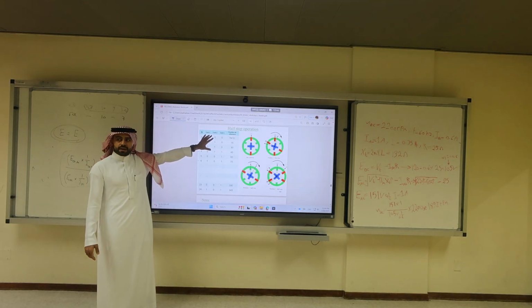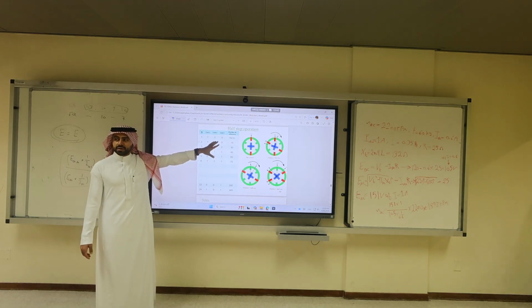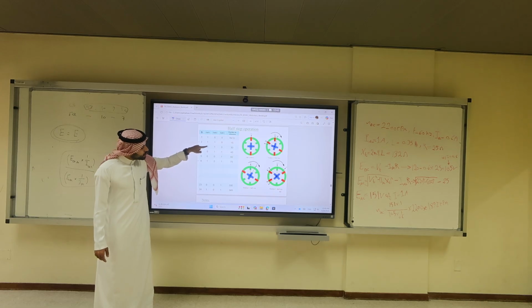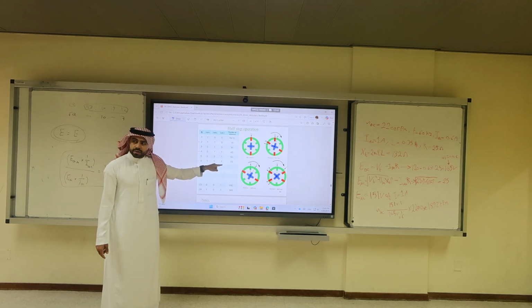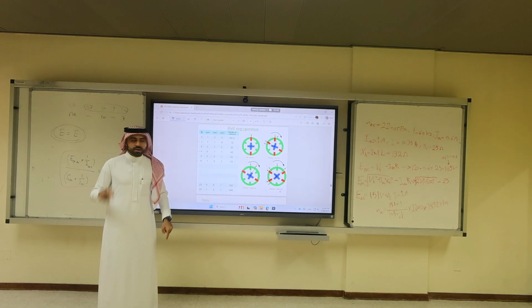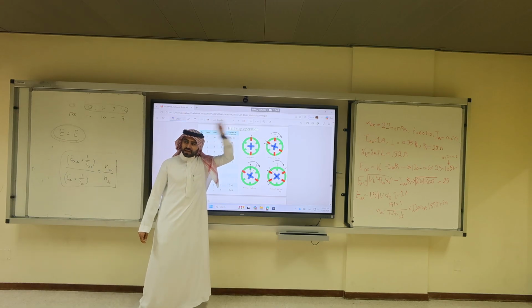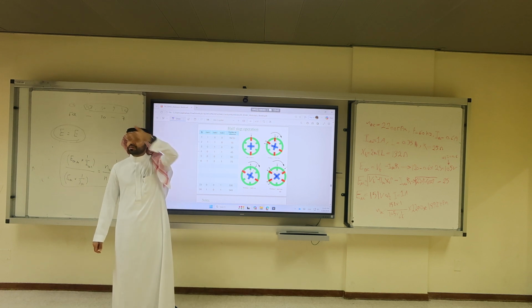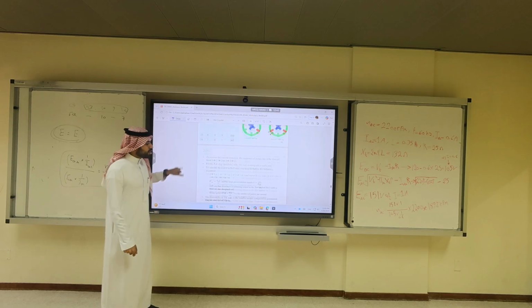Maybe I'll bring it in the exam. Let's call it the double coil full step operation. If I skip the single-coil patterns, I only have 1, 1, 0, then 0, 1, 1, then 1, 0, 1. Then I'm going to have higher torque because I'm putting more current in the coils. But I still get the 30 degrees. So this is one type of operation. You're not only limited to full step and half step. You can have your own using power electronics.